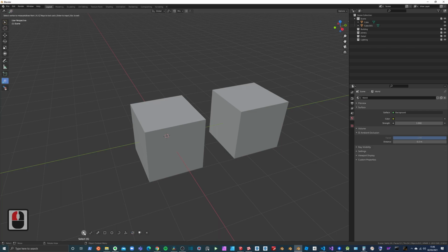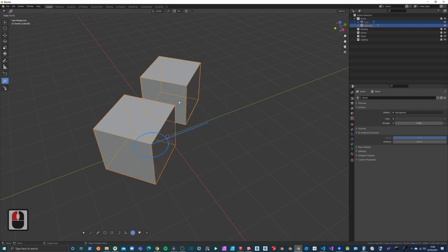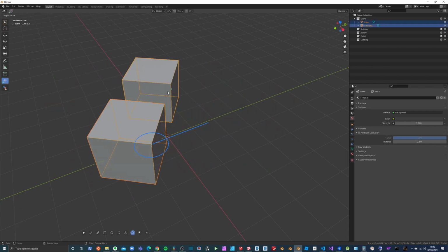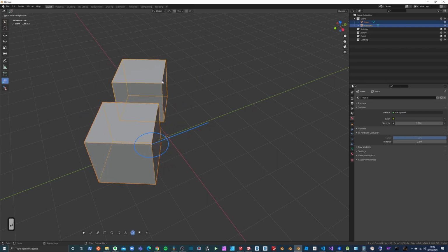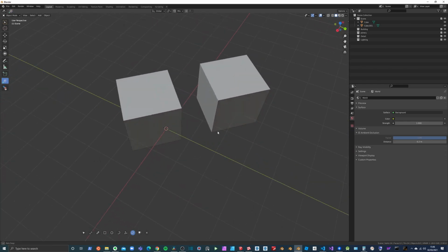I can also do multiple object rotation, so I can select two objects or more using control, select my first point, and then we can rotate both of them. And if I hit enter, just like any other tool, it enters me into the input mode, and then I'll type, in this instance, maybe 45 for 45 degrees, and then hit enter again. And that sets my objects rotated exactly at 45 degrees.